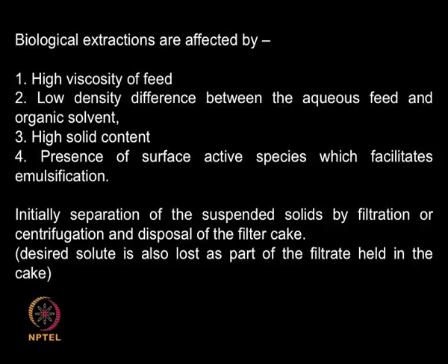Now there could be many surface active species present which may lead to emulsification of your extraction. So at the end of the extraction, instead of getting two clear distinct layers, you may end up with multiple layers. You may have a foamy layer in the middle, you may have a solid layer in the middle. So instead of 2 layers, you may have 4 layers.